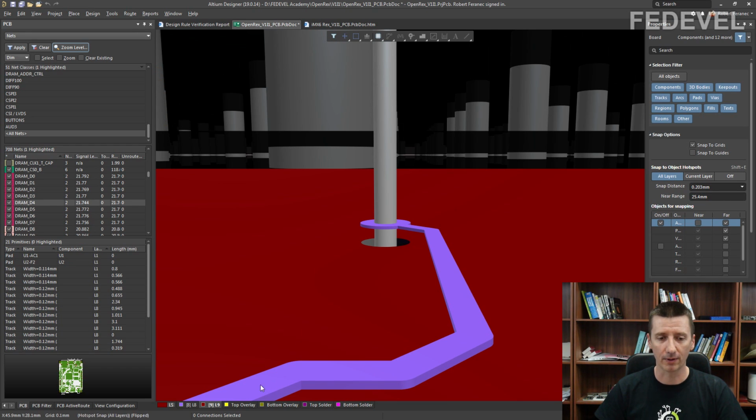Here we have an example, okay? This is a track, this is a via, this is a reference plane. And basically when you are drawing this track, which is here, you are drawing one part of a transmission line. Okay, a transmission line is what is used to transfer the energy. What is the other part of this transmission line?